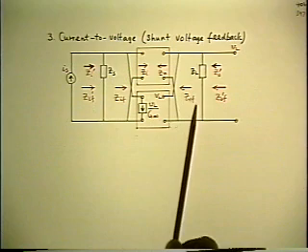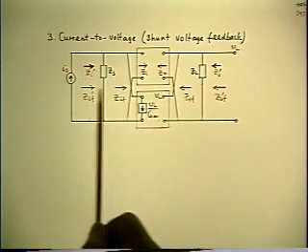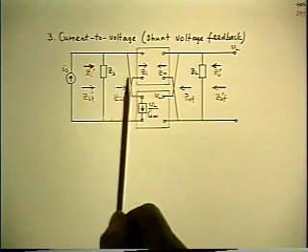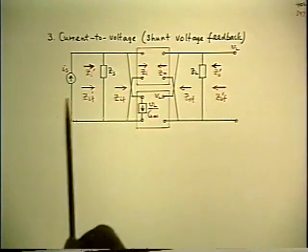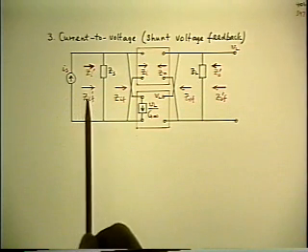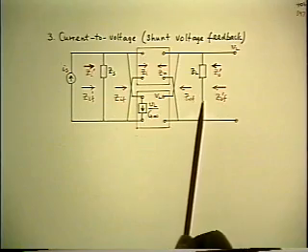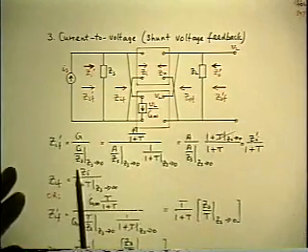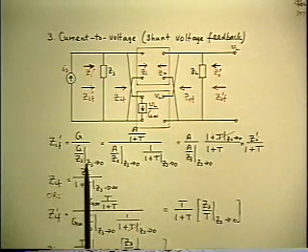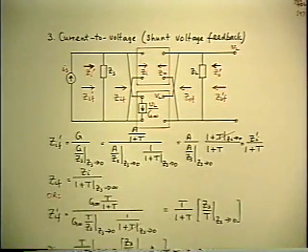But now, obviously, we do just the opposite from what we did at the output, because I've carefully drawn the configuration now to show that the input circuit is identical with the output circuit. So the new formula that we need for the input impedance is exactly the same format as the original formula for output impedance, except we substitute ZS for ZL, and all the corresponding results are the same.